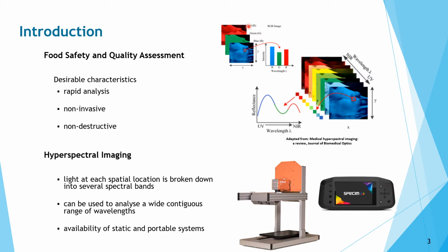The main difference when it comes to hyperspectral imagers is that instead of having three broad bands, we typically have hundreds of very narrow bands. So instead of just a broad R, G and B band, in this case we would have a number of contiguous bands that cover the entire spectrum, but that allow us to have finer detail at each wavelength for the target that we are looking at. So at the end of the day, we end up with an image where for each pixel we have a spectrum which is represented with a good resolution.